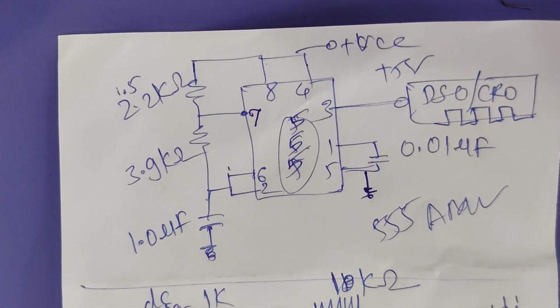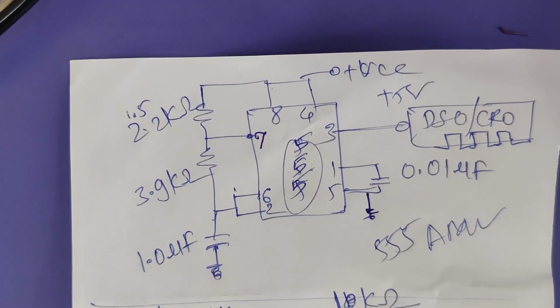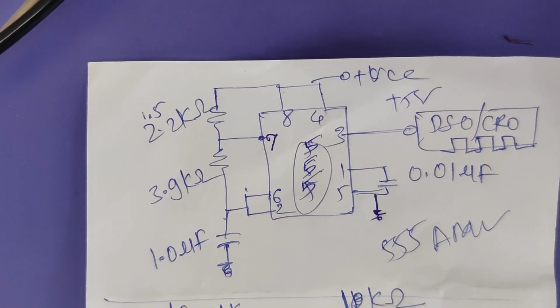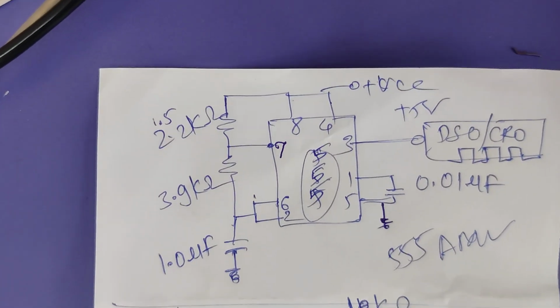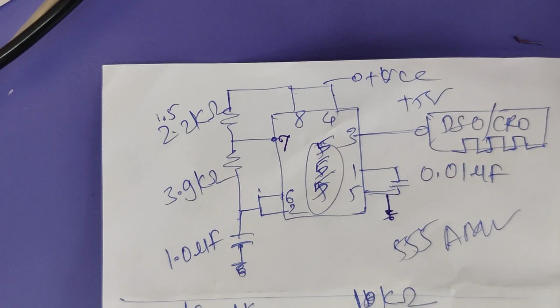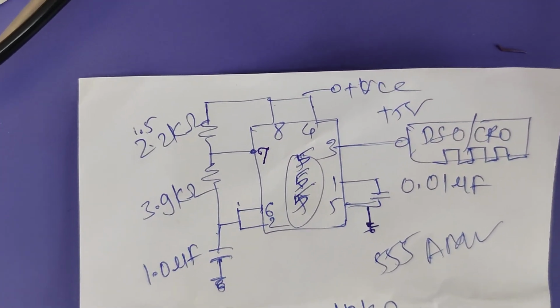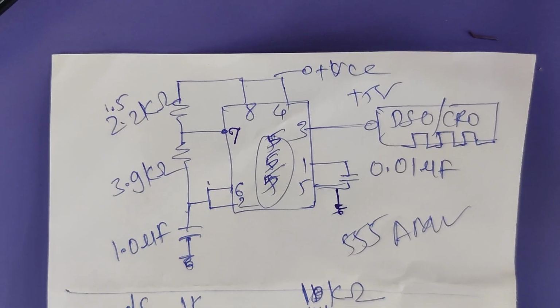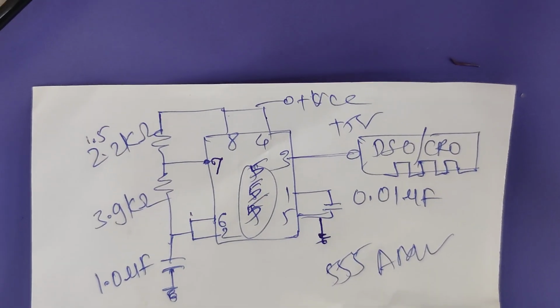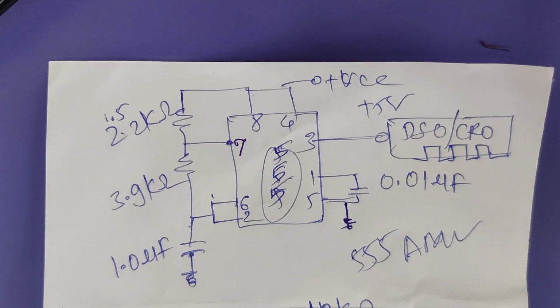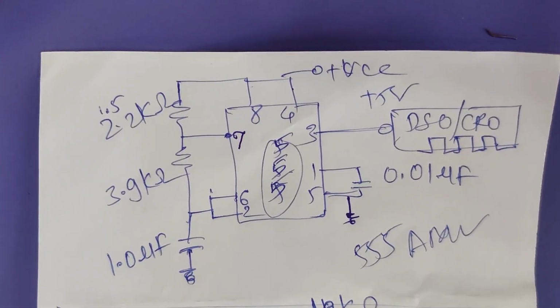Just now we had only the setup to check the output first. For the charging time and discharging time, and also for the frequency, specific formulas are there. Now in this circuit diagram, would you tell me which resistor is responsible for T on and which resistor is responsible for T off? What is the charging path and discharging path of the capacitor?